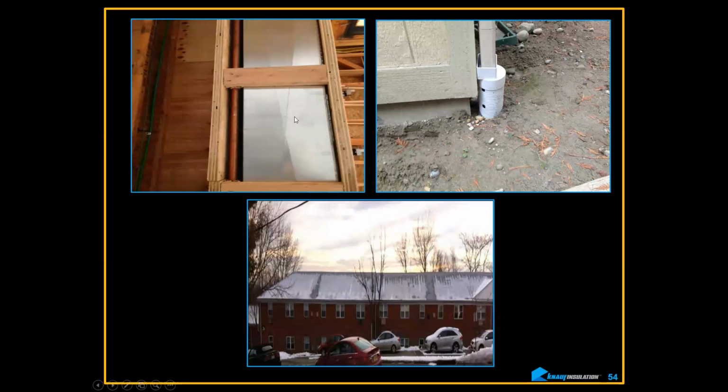So when it's heating, if it's a cold water pipe, this is going to sweat. If it's cooling and this is a hot water pipe, it's going to sweat. There's no insulation on it. Geniuses, absolute geniuses. They're not thinking. Another genius move. Why don't we take all the water from the gutters and the downspouts and make sure there are enough holes in the pipe so that we can soak against the foundation before it gets into the drainage tile down below at the footing.